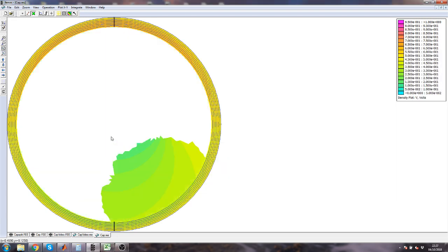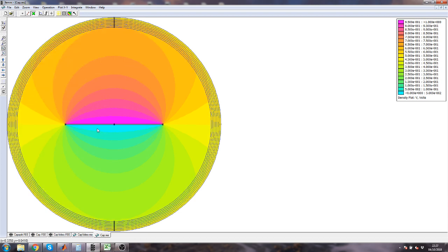So I just wanted to make sure that the parallel plate approximation will be valid-ish, and the key thing that determines that is there is not too much fringing fields, which is the fields at the edge, compared to the fields where the plates really are parallel, and they appear to be parallel for quite a long way out. If you're in the middle looking outwards, you see a lot of parallel plate, whereas if you're on the end, you see fringing. So I want to see a lot more middle than I see end, and then the parallel plate approximation should apply.